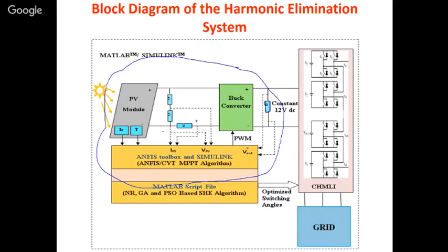At the same time, we were monitoring the input PV. When the irradiation was going low, the PV voltage was also going low. In that case we had to use MPPT, and we were trying to increase the voltage. So we had a different algorithm there, and we were trying to track a constant voltage output. Still, as I told you, a perfect 12 volts was not possible.